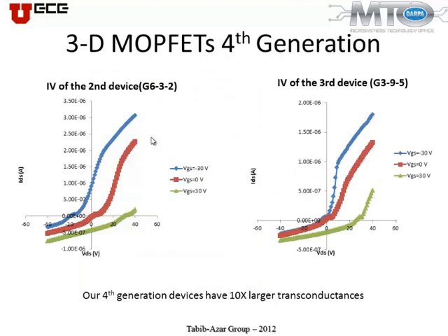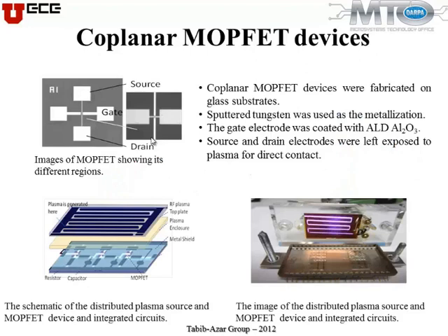And you get a variety of different types of IDS versus VDS. Depending on where the torch is with respect to the gate plate that I showed you, you can get different results. And based on whether you have a three-dimensional or two-dimensional device, that also affects the IDS versus VDS. So as I mentioned, our goal is to make this transition as sharp as possible and separate these curves as much as possible from each other.